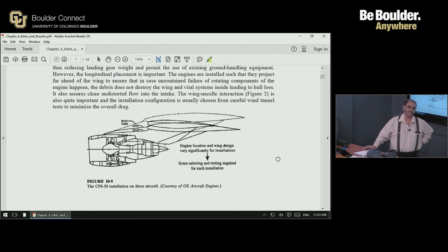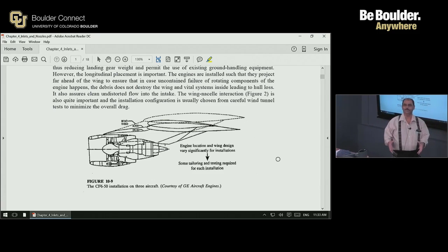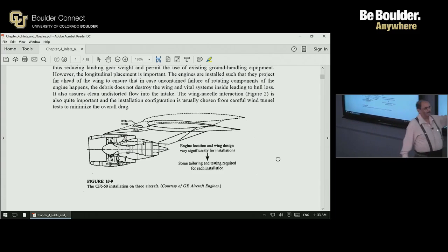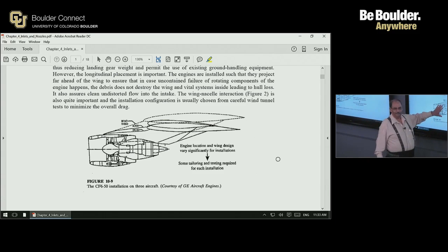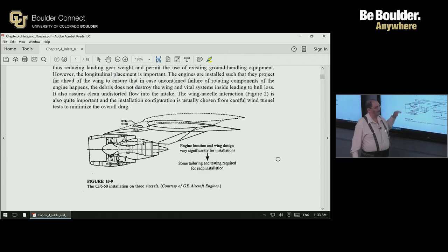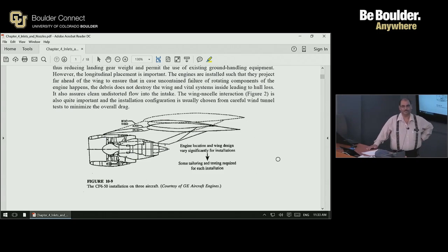And therefore the design was such that the landing gear didn't have to be too long. Now you take that engine, that landing gear design, and the fuselage design, and then you want to hang a large diameter fan underneath. What do you do? You just don't have enough clearance if you hang it well below the wing. So the Boeing engineers worked very hard to figure out how to mount that engine almost level with the wing, and still not cause too much additional drag.